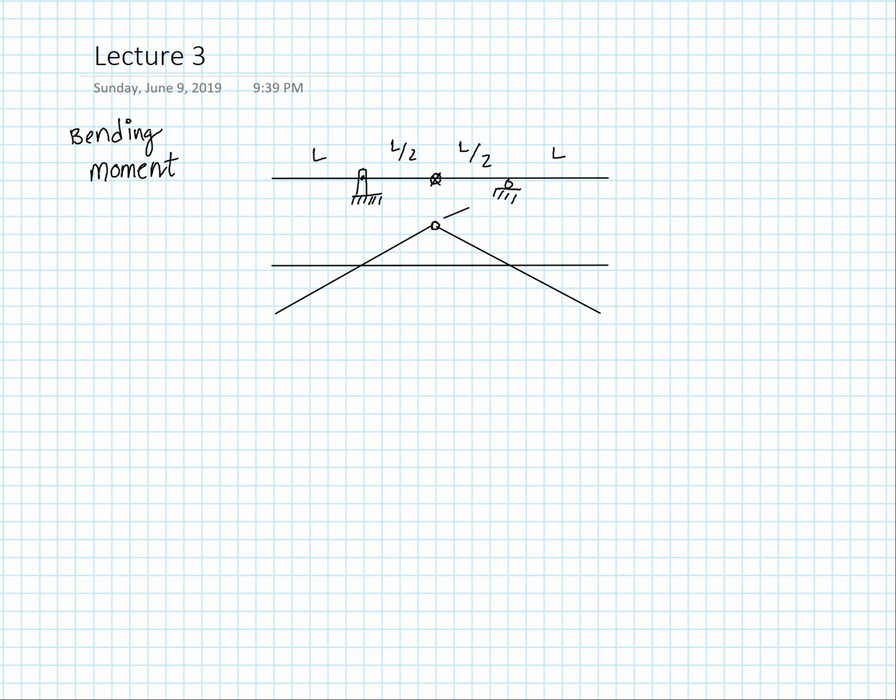And I'll explain to you what we're doing. So based on this principle, anytime you're finding the influence line for the bending moment, you introduce a hinge, and the total rotational angle of this hinge, so between this arm and this arm, this rotation must have a magnitude of 1.